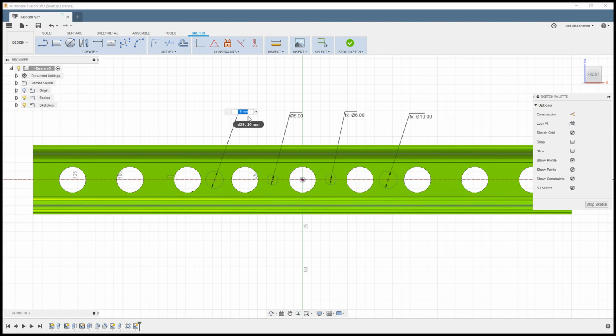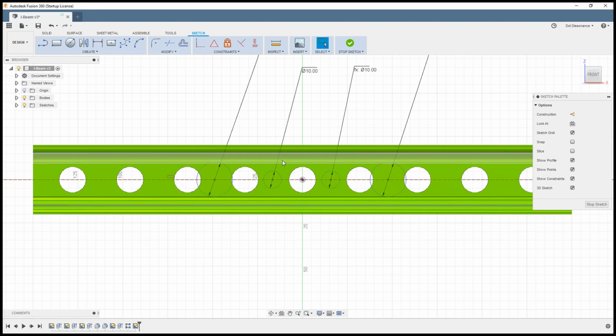So you take this one and you say, I want this one to be the same as that one right here, dimension 27, and then just simply say times 2. Okay? And now because this one is associated with this one, and that one's associated with this one, everything should go all hunky-dory. There, see? So now if I change this one back to, let's say, well, how about 5 and 10? If I change it to 2, then they're 4. If I change it to 10, they're 20.